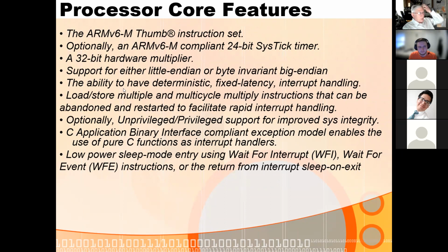So the one really nice feature of this chip is that it has very fixed latency interrupt handling, which means that when the interrupt occurs, you have a real guarantee of just how long it's going to take before you're in your interrupt service routine. And that is really helpful to eliminate jitter when you're sampling.